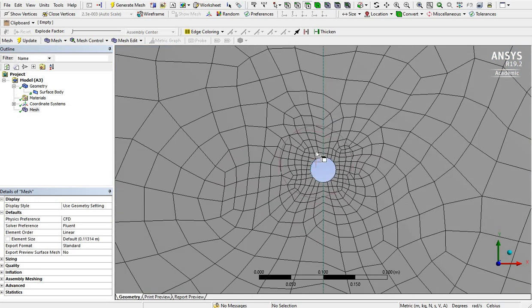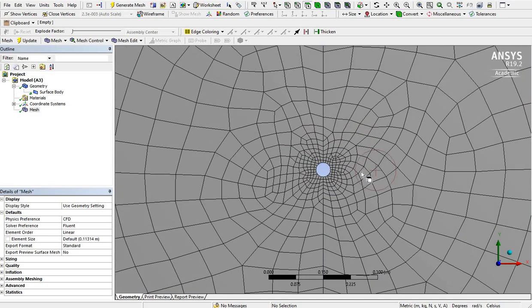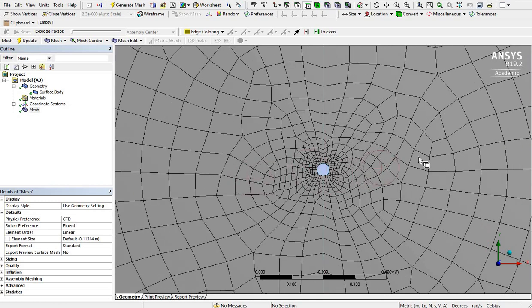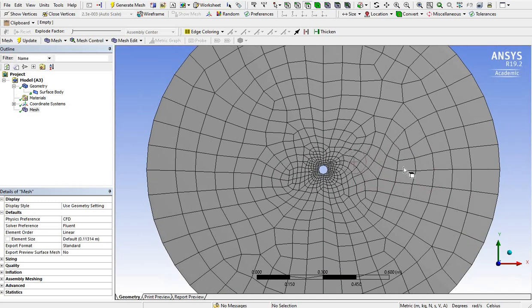It will change in here and then behind. So what we say is wake of the object. Okay, wake of the cylinder. Behind the cylinder, the flow will fluctuate depending on the Reynolds number. Along the whole endpoint, it might fluctuate or start shedding vortices after a certain Reynolds number, or it will stabilize depending on the Reynolds number, depending on the flow.